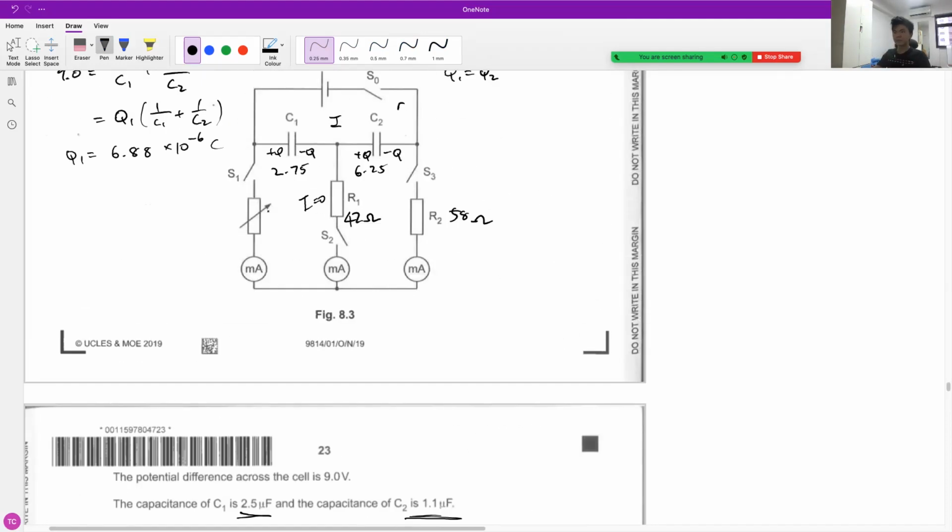If we apply Kirchhoff's voltage law, first of all we know there's current flowing through this blue part of the circuit, and let's call it I. The reason we can call it I is because no current flows through R1. Whatever current comes in this junction must all leave through this junction as well, because no current is redirected into R1. So that's why we label it like that.